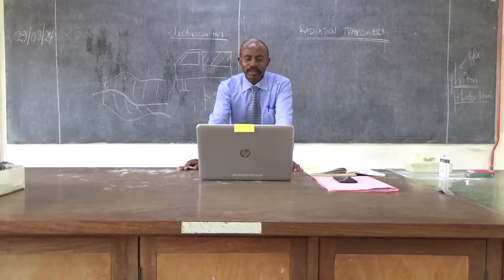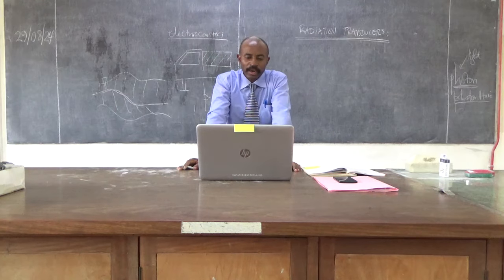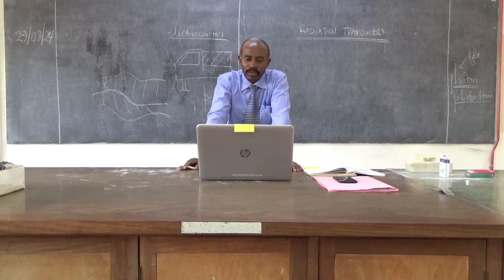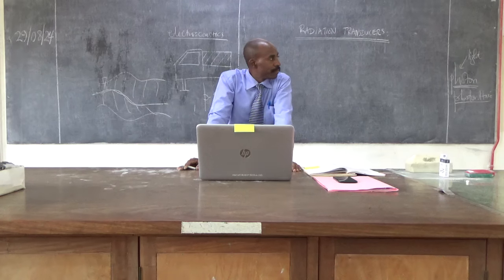So measurement of ultraviolet radiation cannot be made if the transducer is contained in an envelope of window glass, or if the radiation must penetrate window glass to reach the transducer. Often the process of radiation transduction is linked to a particular source of radiation. It is essential that the transducer and the source be matched with regard to energy.